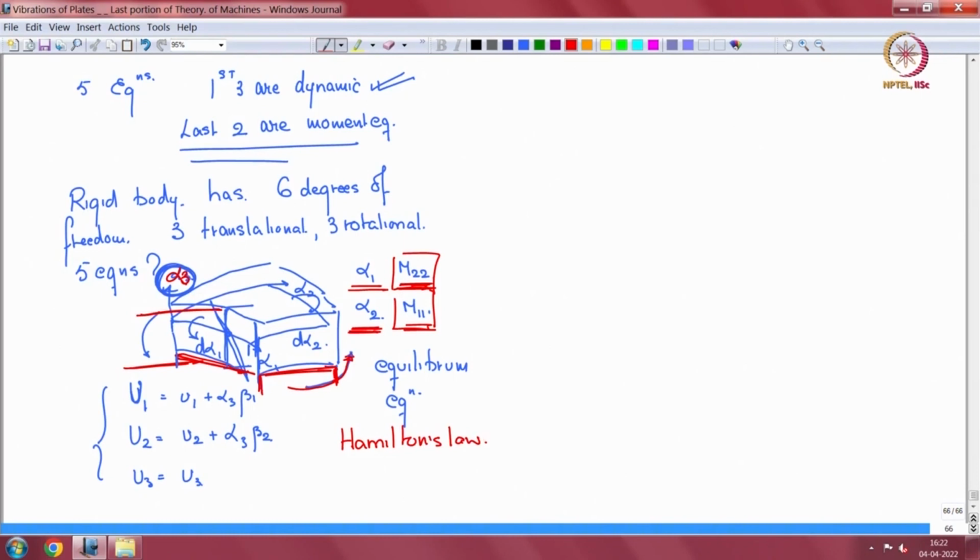What that means is that u1 and u2 will account for all that is happening to this element in the plane of alpha 1, alpha 2. Separately, you will not get a rotation equation, which you do because of the finite thickness in the alpha 3 direction. Okay. It is not that rotation is not accounted for, it is accounted for in u1 and u2.